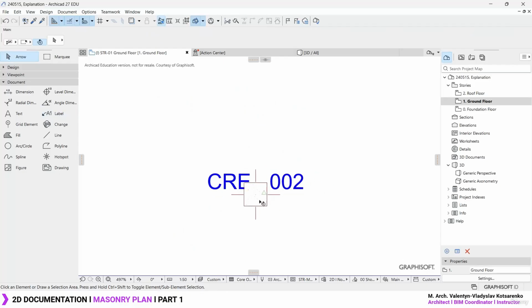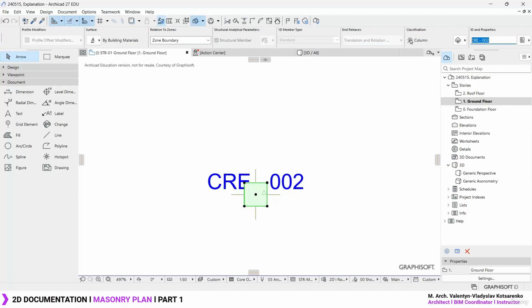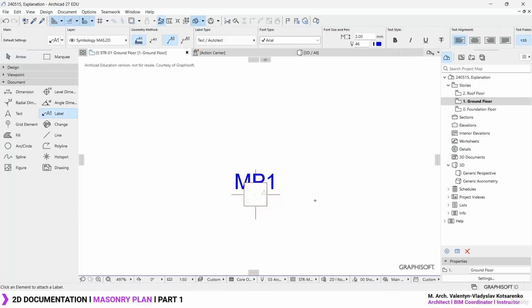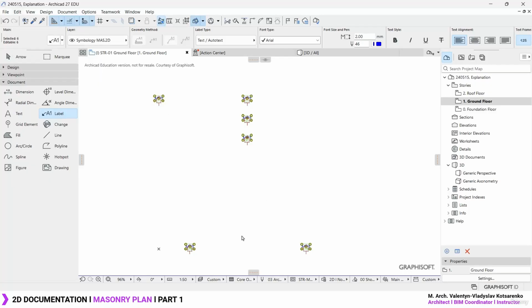This is the amazing thing about labeling, the labeling process, because you can detect all types of errors quite easily, and masonry pilaster 1, and just fix this real easy. So once again, I'm just going to make sure to have everything corrected. Okay, it's looking good. Let's select the labels and press Ctrl G to group them. You can also go over here to edit, grouping, and simply activate the group button over here, or Ctrl G, however you want to.